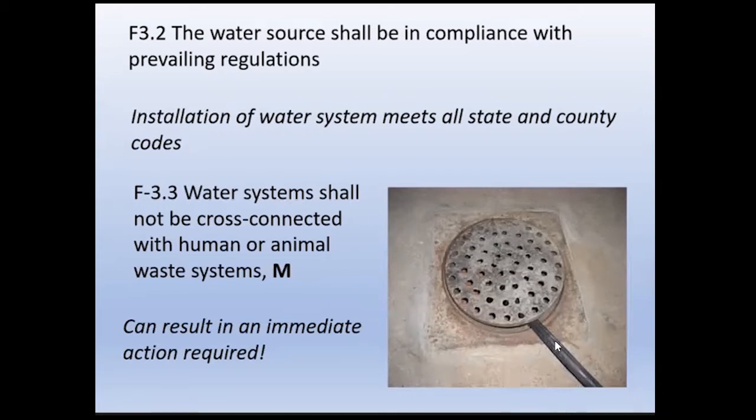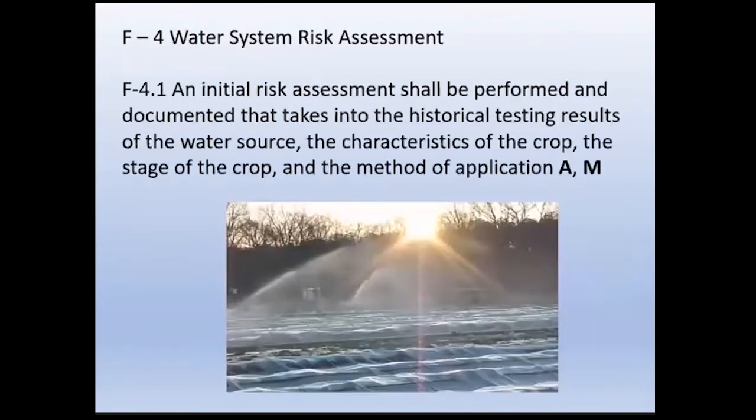Because it keeps the condensate water off of the floor, which we don't want. There's many, many risks associated with that. And this works fine until the drain backs up. And now you have contaminated water going back into your condensate line, and that's a risk that you don't want to take. So be careful on these shortcuts that you might take. It might get you into trouble down the line. It can be a risk.